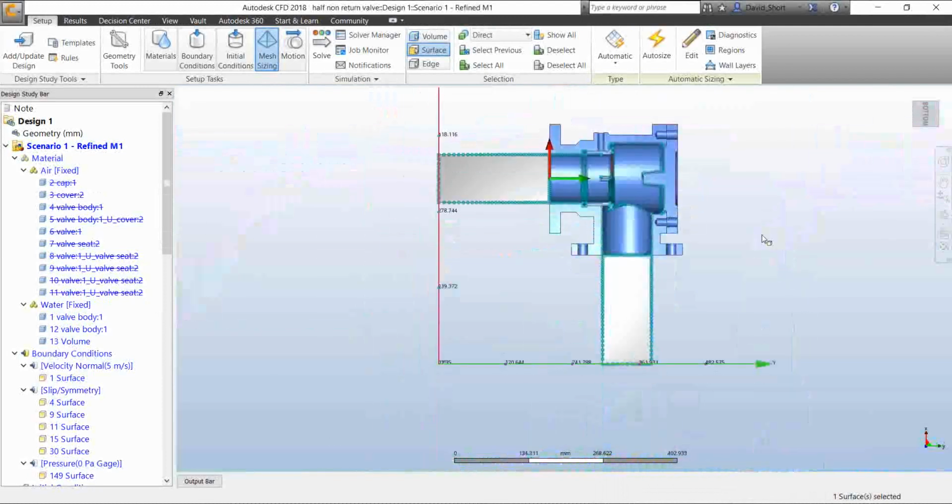Also in CAD, I extended the outlet and inlet. I could have actually gone a bit bigger here, because it's good practice to have 5 times the length of the diameter of the inlet and outlet to help your simulation avoid recirculation at the outlet.